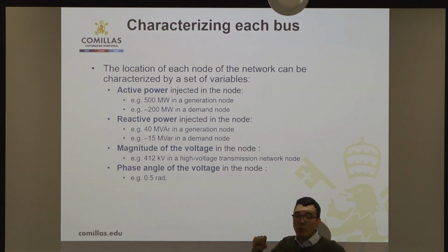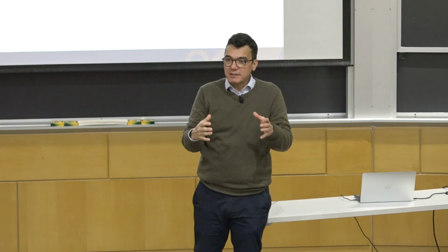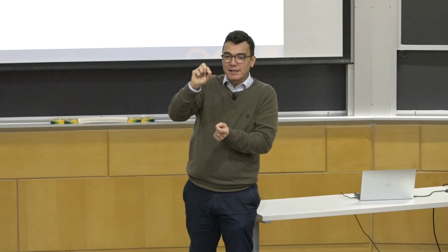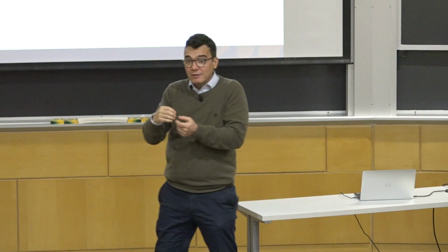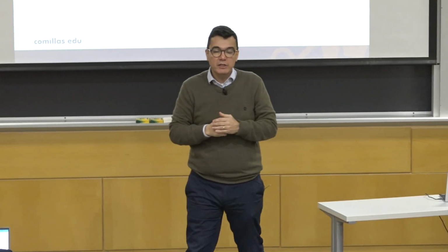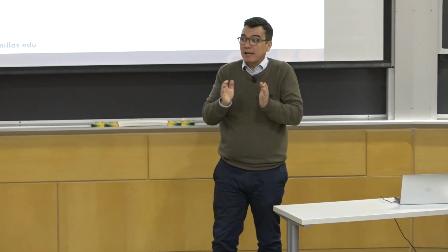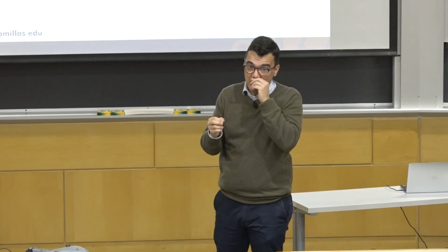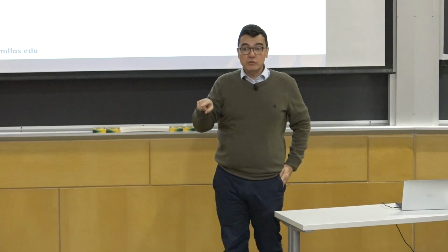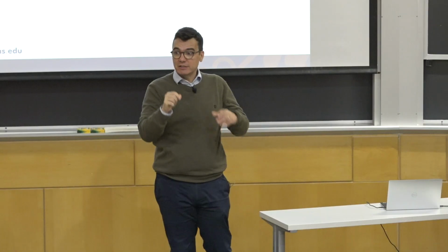But you also have reactive power, and you have consumption of reactive power because, as I said before, if your load is a mixture of inductors, resistances, and capacitors, whenever you feed this load with a perfectly sinusoidal wave of voltage, the current will be a sinusoidal wave if we don't have non-linear loads, but the current will not be in phase with the voltage. Okay? It would be a causality that is perfectly aligned otherwise. So you're always going to have a certain amount of reactive power being consumed. And the generators are able to control the amount of reactive power that they inject.